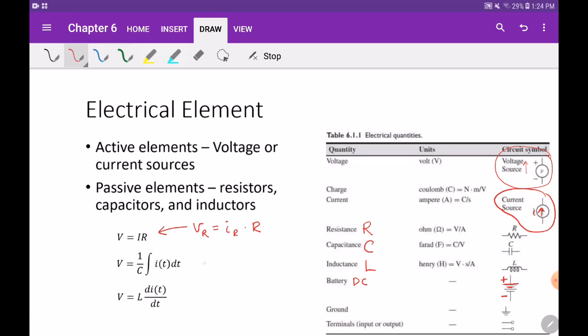So similarly, the voltage drop across the capacitor is equal to the charge divided by capacitance, where dq over dt is defined as the current. So sometimes I use current with a capital I, and sometimes I use small i. I really should be using small i, but sometimes I want to use di over dt, and this will look a little funny, with a dot on top of another dot. So sometimes I just use the capital I to mean it's a function of time instead of S domain.